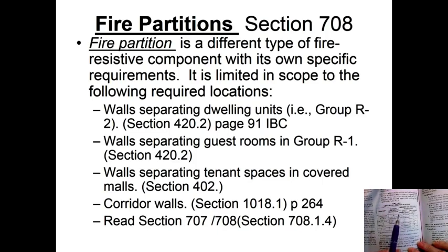So that's why you see, and you'll notice that this particular table talks about the occupancy, talks about your occupant load, okay? And then it tells fire resistant rating without sprinkler system and with sprinkler system. So a lot of times a hazard, it's not permitted. It's going to tell you you have to have a sprinkler system. And some of them still give you ratings.